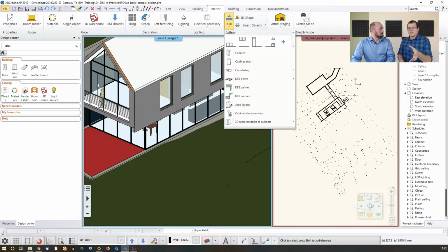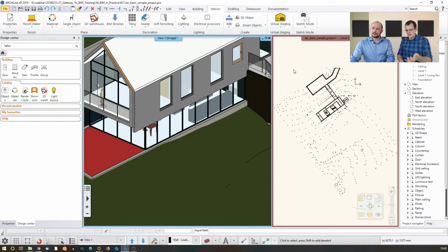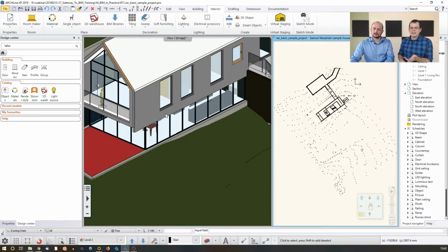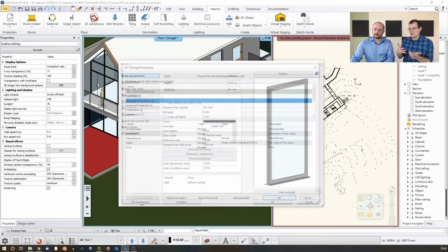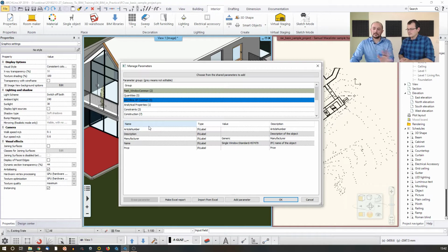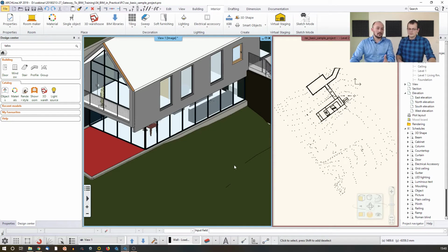So to sum up, there are three kinds of objects which come with an IFC file. The first category is the best category, because then you can modify these. You can change the heights, thicknesses, profile them, etc. Second category are those where you have to decide if you want to make the 3D unfixed and make some changes. If you do that, you might need to adjust the elements later on. And the third category are the things which you can see and you can access the data, especially the BIM data, but you won't be able to further edit them with the same ability as they were created in the software where they were created. Yeah, that's right. The BIM data is always kept, however the situation is, but the editability and the way you can treat them is various actually.